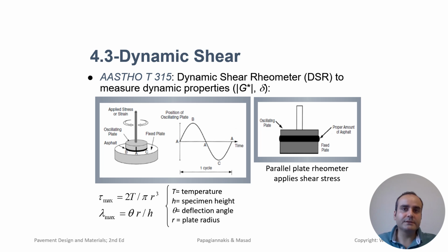Dynamic shear modulus is a measure of the binder's stiffness under dynamic cyclic shear loading. This property is critical for predicting how the binder will behave under traffic loads, particularly in resisting rutting and fatigue cracking. Complex modulus in this test represents the total resistance to deformation, elastic plus viscous.